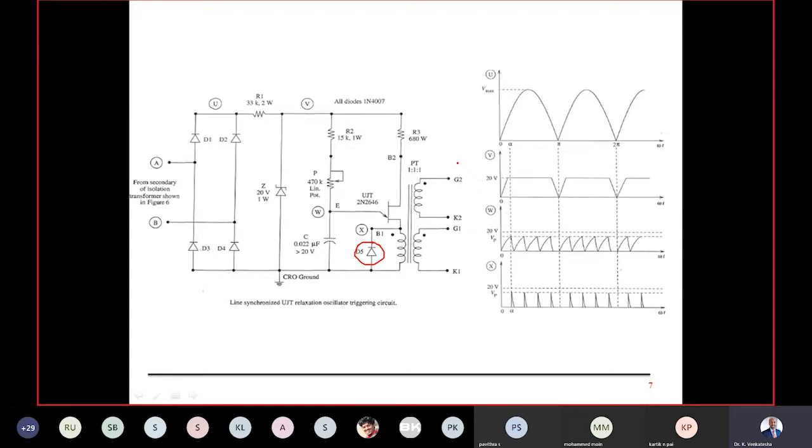In entire power electronics, whether it's an inductor or capacitor, if we talk about the inductor, it has to energize and de-energize. You should use the words, as I told you, energize, de-energize. You should reset it, otherwise, only then will it energize freshly, capacitor, inductor, right? Now what will happen here? When the switch is turned on, the inductor is energizing in this particular path. The capacitor reaches the peak voltage here. It starts discharging now through my switch. Now, this is the path available here for the inductor to energize.